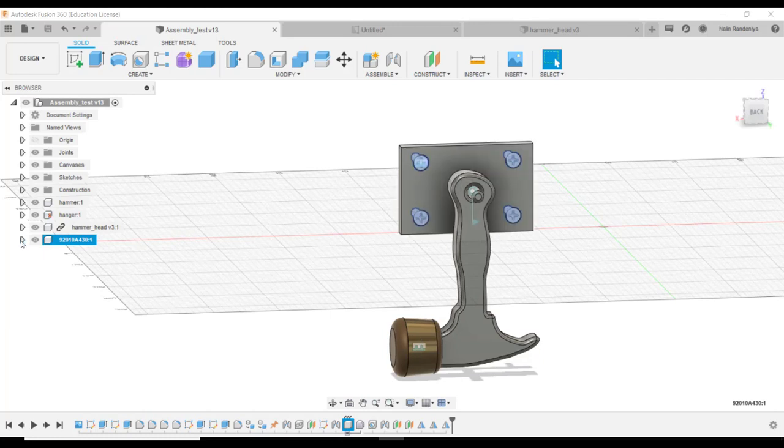So when I open that component up, I got the bodies. I got 1 2 3 4 of them here. Remember, when we duplicate them, what we just did, we mirrored them across. So when we mirror them, if they don't go as components, they just copy as bodies. So you need to avoid that when you develop your models. The best way to do that, I think I vaguely remember I showed how, is copy paste. So that is how you're supposed to do that manually.